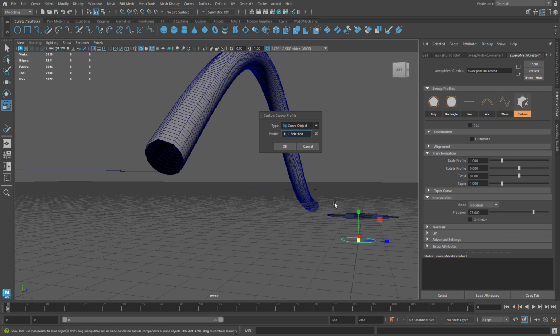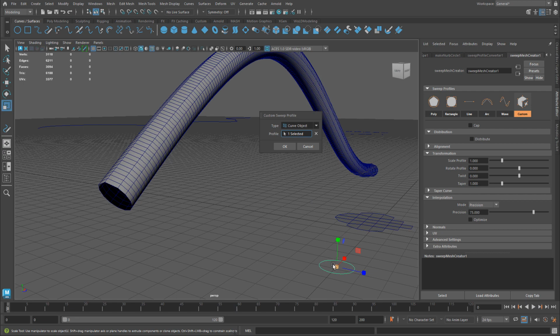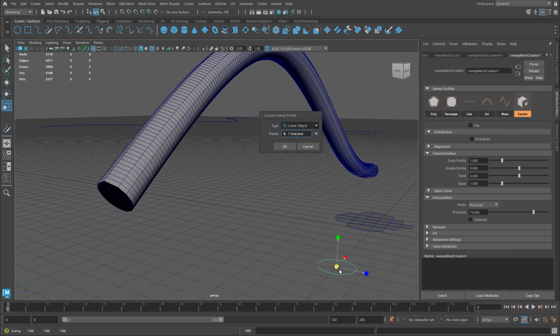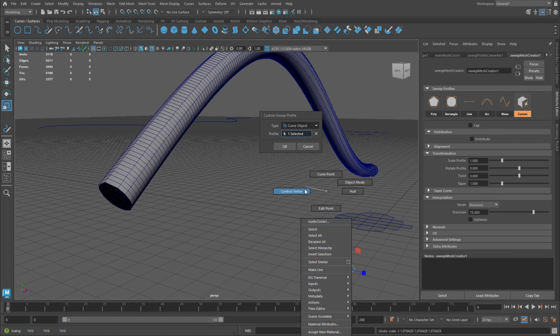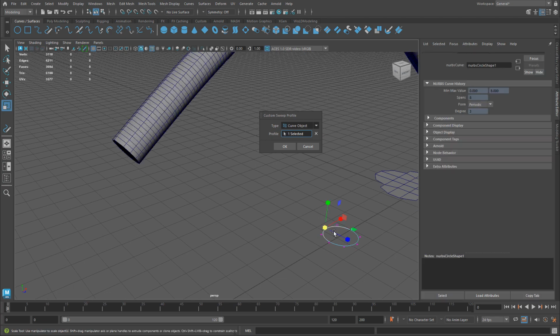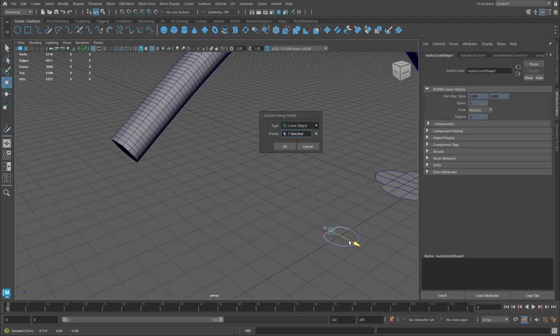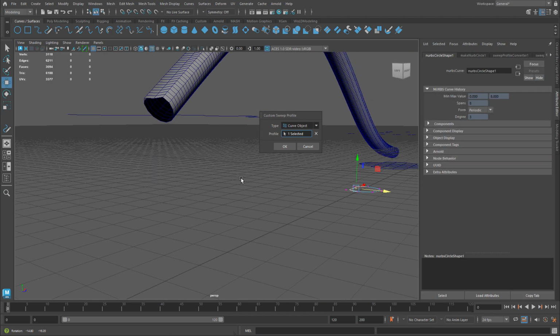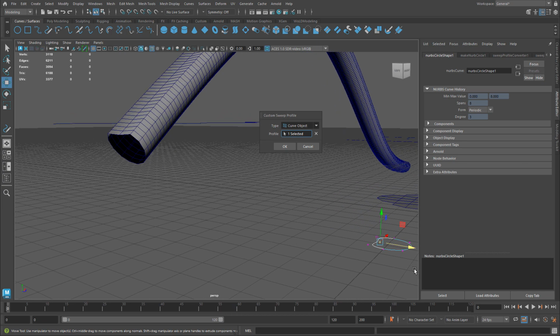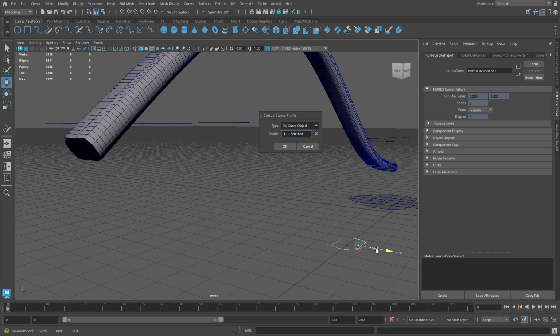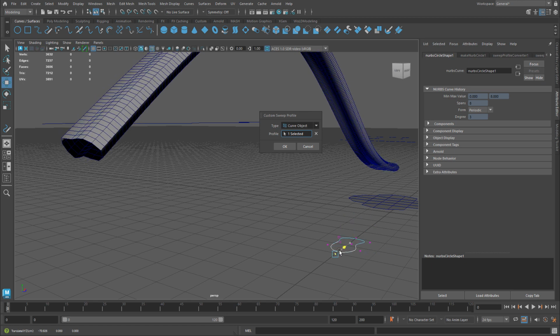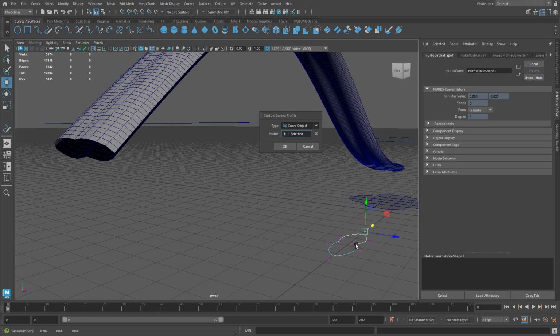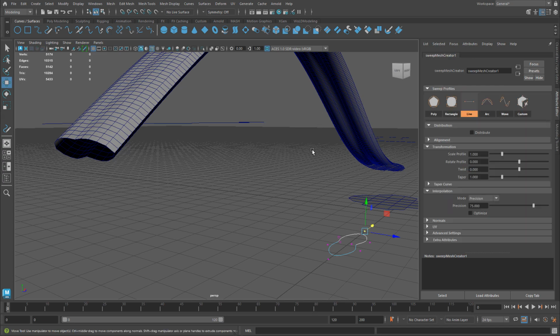And here's our geometry. Now, of course, I can just select the curve again. I can scale it. I can switch over to Control Vertices and modify the shape of this, and update my profile. So you can have polygonal objects as well as curves that you extrude. So as you can see how powerful this can be.